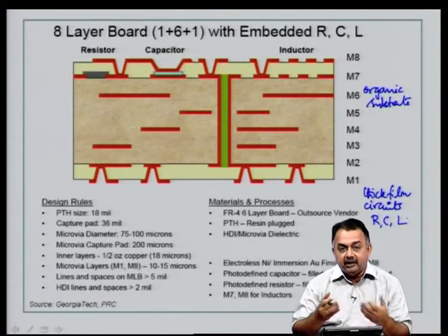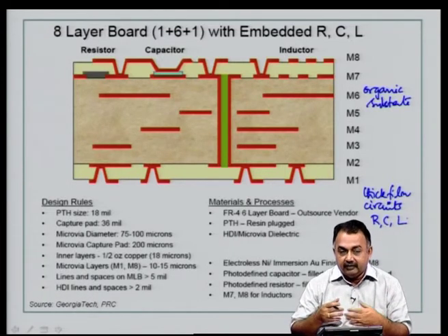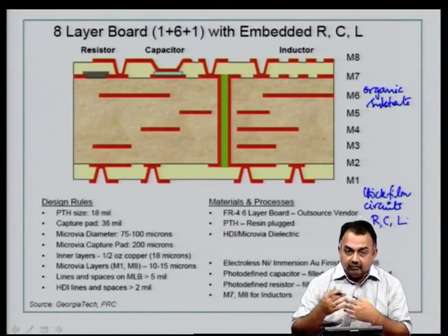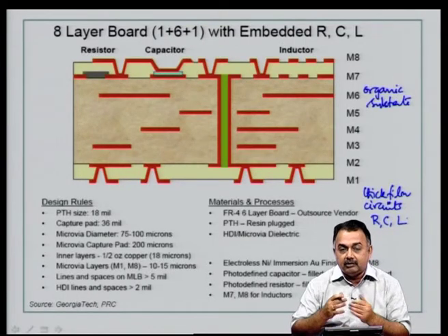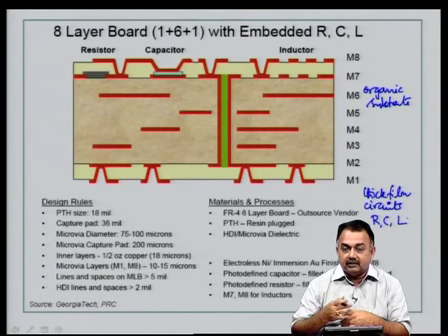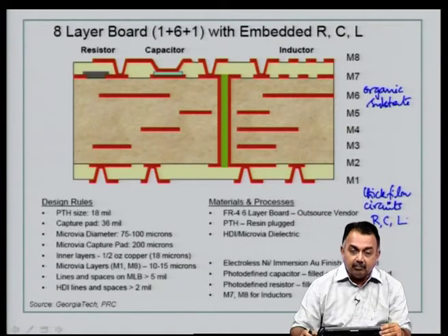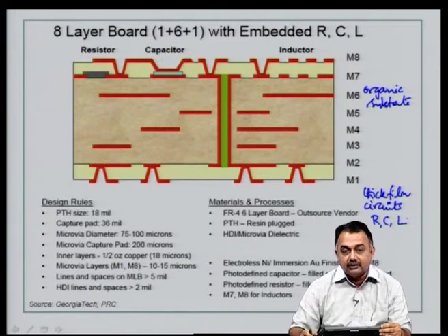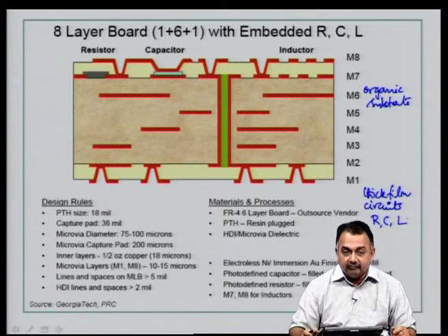in the form of inks printed on ceramic substrates, and they will be co-fired at fairly higher temperatures varying from 500 to 1000. In LTCC it is typically between 300 and 500, and HTCC from 600 to 800 or 900 degrees depending on the material substrate that you have chosen, and they form interconnects during the co-firing.